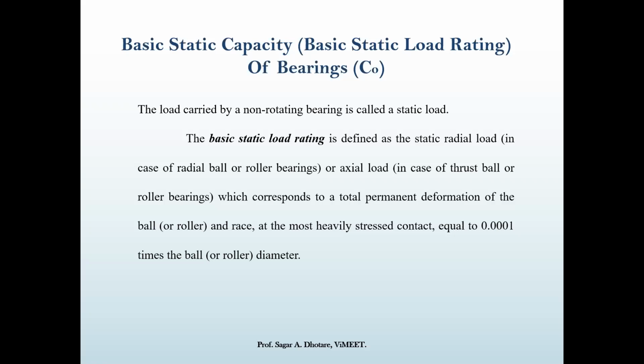Okay, this value of basic static capacity is given in a manufacturer's catalog, as I said previously also. So based on this catalog value, we need to choose the bearing based on the application, as we have already discussed in the first lecture, which type of bearing is used for what kind of applications.